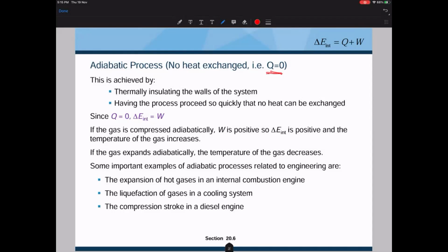It applies to a can of compressed air as well. So you just release the can of compressed air, it expands to the surrounding, and the gas inside would not have much chance for the heat energy to come in very quickly. So that would be considered as adiabatic. So when the gas is expanding adiabatically, it would have to do the work.